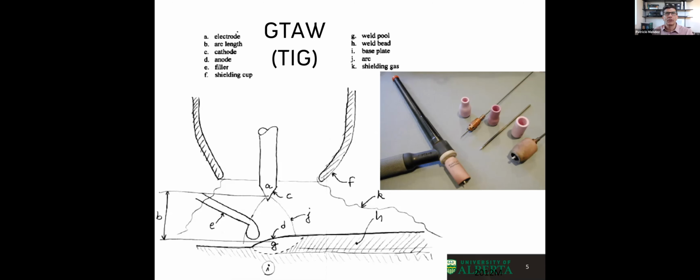The way we use in TIG, and it's the simplest, is we blow some amount of inert gas, a noble gas. Could be argon, could be helium, could be many other things like krypton, but we don't want that because it's too expensive. Argon is distilled from the atmosphere, so it's relatively cheap. Helium is a non-renewable resource and it's a lot more expensive, but those two are available.